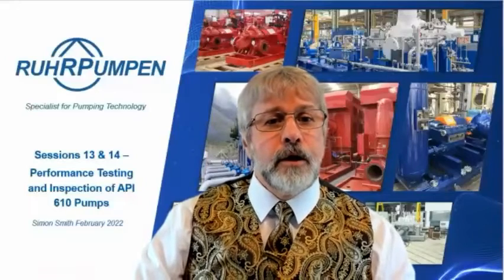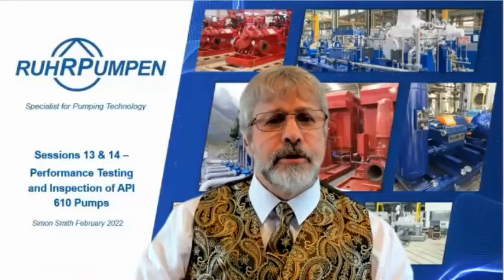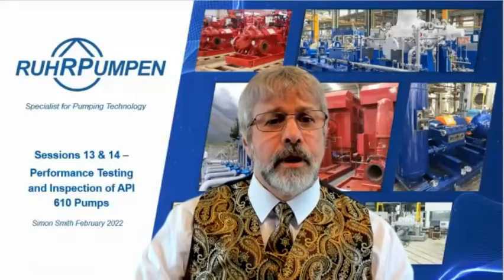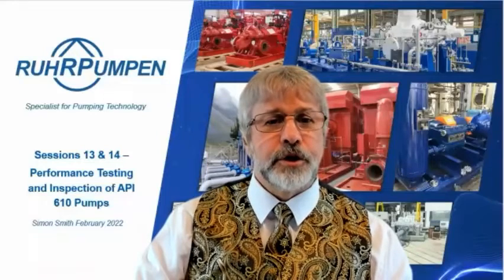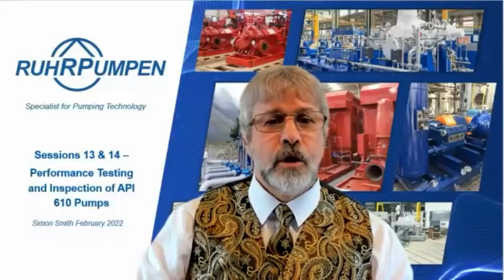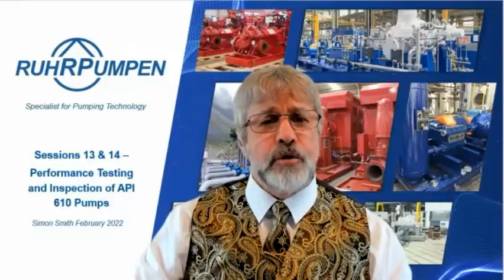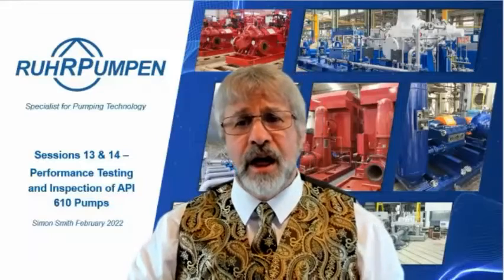Mohammed Shafiq, we've done the test for OH2 pumps, A and B, by using an orifice to meet the customer requirements. But we got different pump performances for both A and B. As per the test, the pump A is okay with good performance, but pump B had shown a hump after the minimum continuous flow point, which means the head rise to shut off is not continuously rising. So could you please tell us the best solution to have the pump with continuous head rise to shut off? What can we do best to achieve this? So what I'm hearing here is your pump A showed a continuously rising curve and pump B showed a hump in the curve.